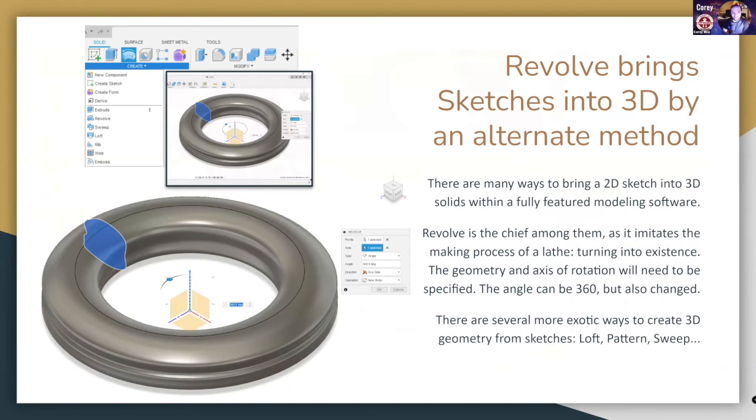The next way that I think is worth putting in as a main way to build something is with the Revolve tool. In addition to extrude and sketch, the Revolve tool will let you build things where they're rotated around an axis. And for this, it's a little bit different, right? You're coming into 3 dimensions. There's some curve that happens naturally with it, but you're specifying a shape. I was trying to go for a weird donut-y shape here. You have a shape, and then you need to have an axis of rotation that you're going to spin around. And I'm spinning around just the y-axis of this entire part.